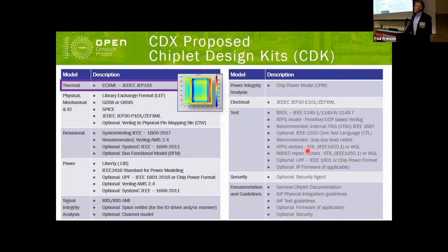Now, the resolution of the model needs to be sufficiently detailed so you can perform an accurate enough SiP level analysis. We're going to leave that to the discretion of the chiplet designer, because they know where the hot spots are. But the recommendation is to make sure they provide a model that's accurate enough so it does provide useful information. Now, chips or chiplets often have many different modes of operation.